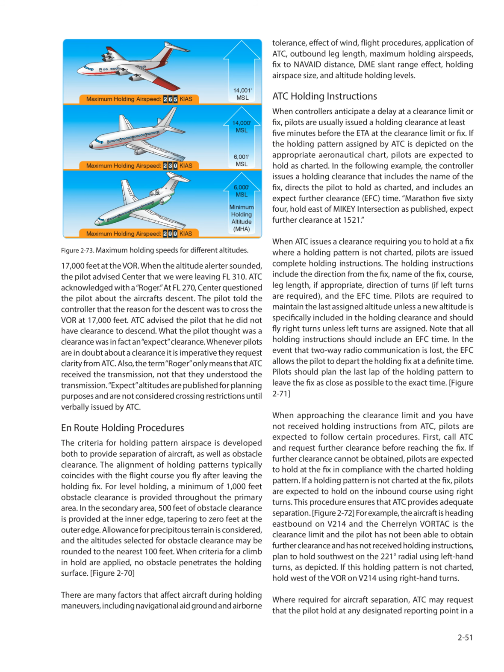ATC holding instructions: when controllers anticipate a delay at a clearance limit or fix, pilots are usually issued a holding clearance at least 5 minutes before the ETA at the clearance limit or fix. If the holding pattern assigned by ATC is depicted on the appropriate aeronautical chart, pilots are expected to hold as charted. In the following example, the controller issues a holding clearance that includes the name of the fix, directs the pilot to hold as charted, and includes an expect further clearance, EFC, time. Marathon 564, hold east of Mikey intersection as published, expect further clearance at 1521.